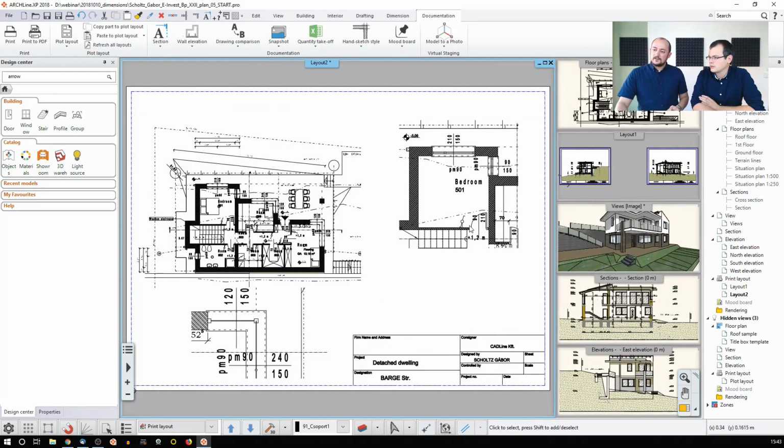I see there that we have a question about how we can do the detailing and other things like that. You can actually make, at any time, a copy of the dynamic content, which is the original section that was auto-generated and keeps the link with the original building parts. You can select that, make a copy, and paste it into a 2D view.